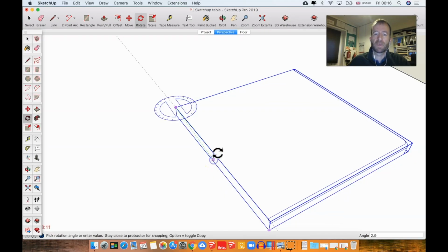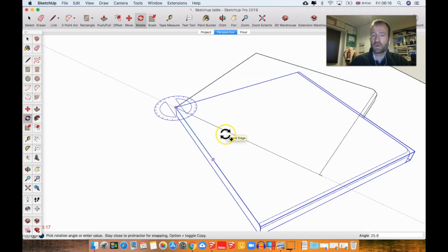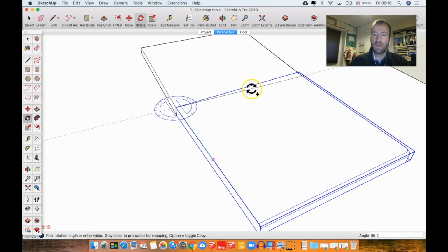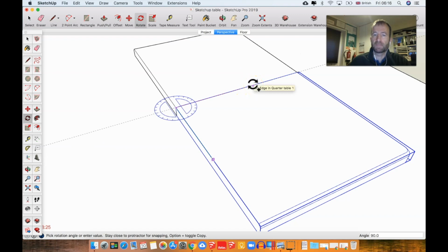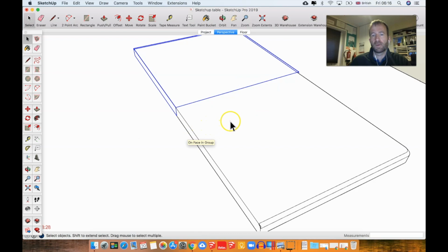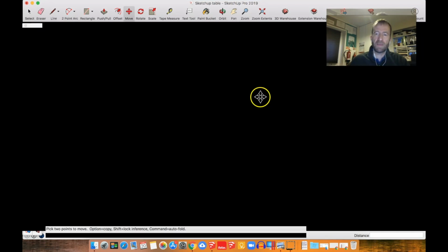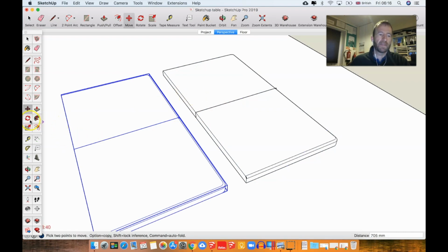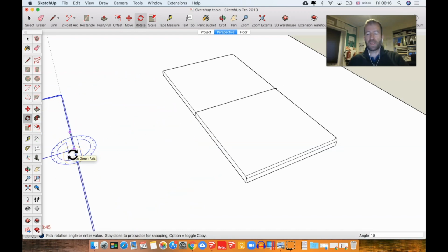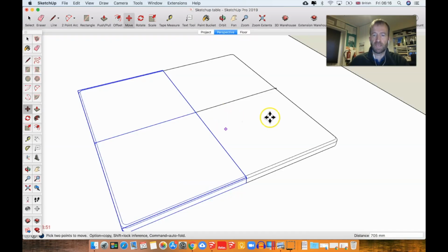That's your second click. Now at any point before you finish this operation, you can press the modifier key, which is Alt on the Mac. I think it might be Control on Windows, and that copies it. So then your final point is at 90 degrees here. And we can then copy both of them. So I'm just going to do a copy move now. So M for move, Alt for copy move, bring that over, and I'm going to just rotate that again around the center and just type 180. M for move again, grab the middle, bring that over there.